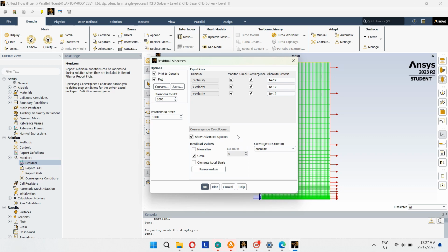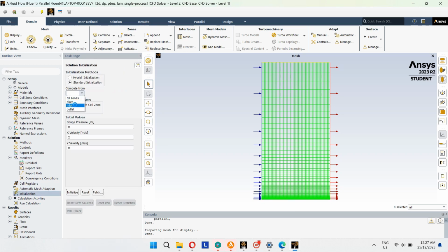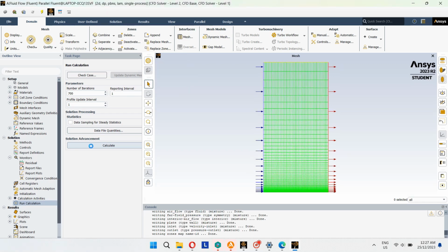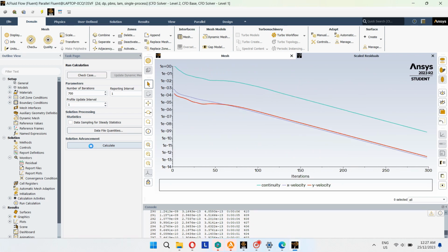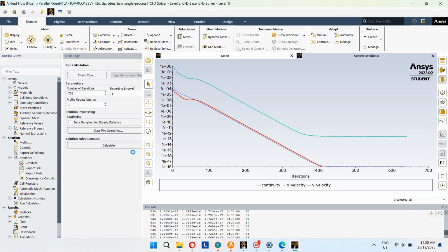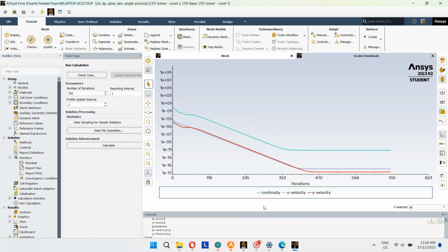and then click to initialize, click inlet and change its velocity to value of 2, and click on calculation and change number of iteration to 700. Number of iteration, the number of the time per specific operation or process is repeated. I use 700, and the limit for the chart is 700 only, and we can see the flow is steady after around 400 and above. That's all for this part, and we continue for the next part.